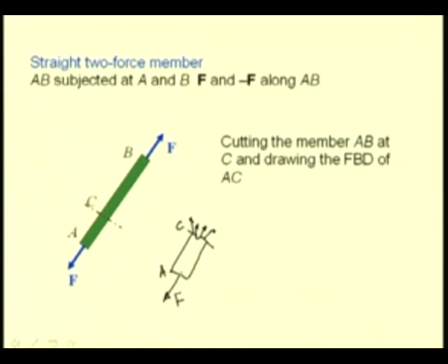And it becomes apparent that if we consider the axis of this member and if we sum all these forces at this section C, they have to be equal and opposite to this force, because this portion is again a two force member. So, we have the resultant of all these forces as F, which is equal and opposite to the applied force.